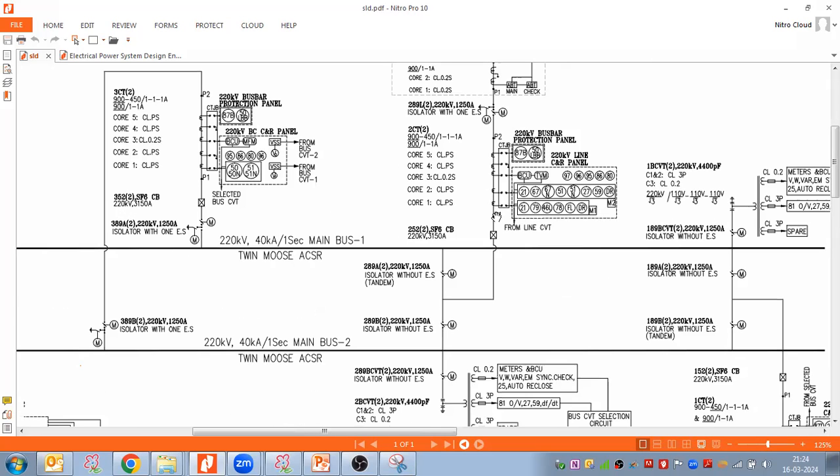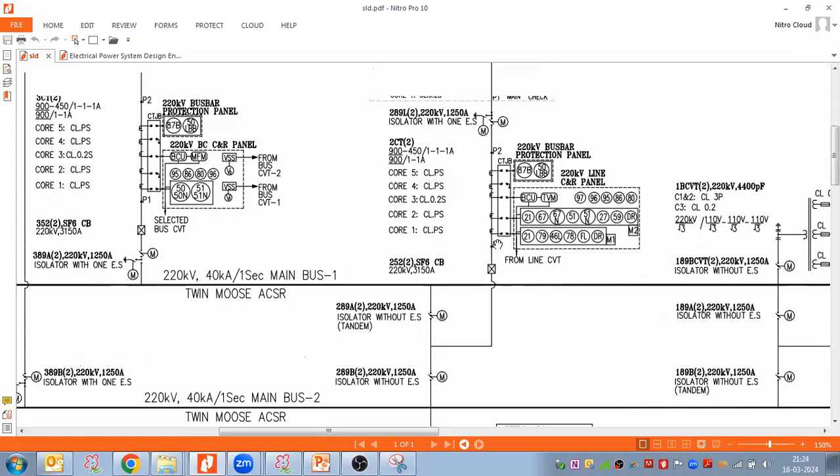So let us start by taking the response of some experienced engineer. If I put the CT not here, before the breaker, so what would be the problem? I need some reply here, please. We cannot take the maintenance. Yes, sir. During maintenance time, let's suppose after maintenance, if we have to close, and there is a fault, then it will not be taken for SOTF function and all.